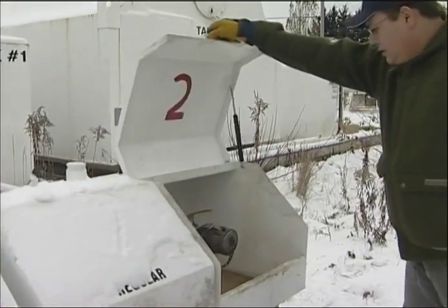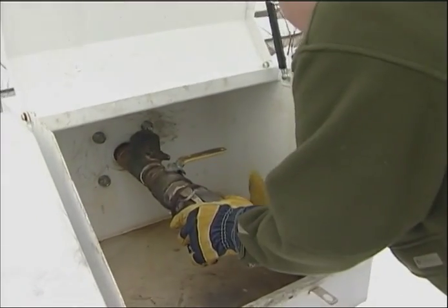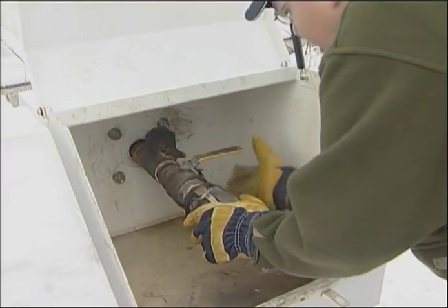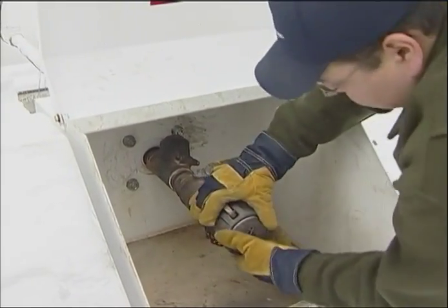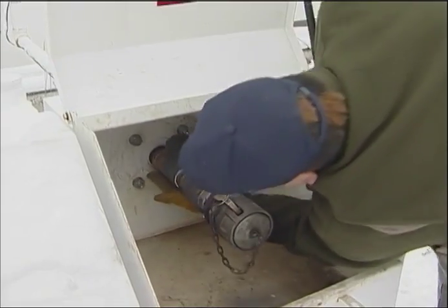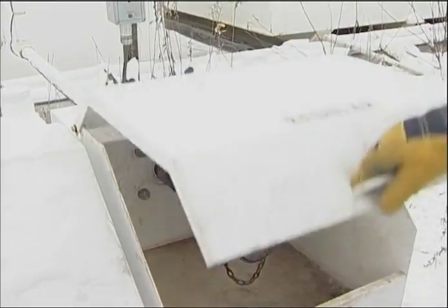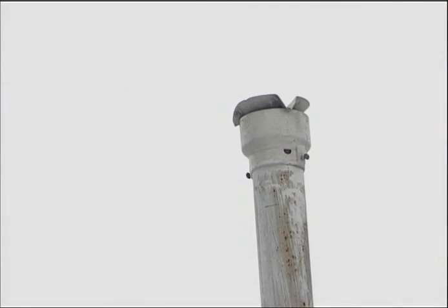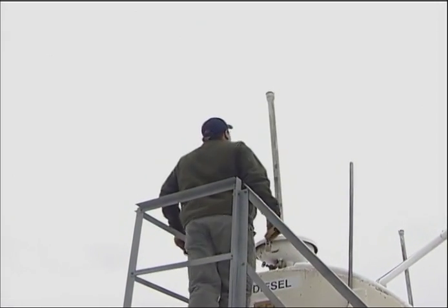Check all fuel shutoff valves to ensure that all valves are in good working order. Check fuel shutoff valves for wear or possible leakage. Check pipe in fuel cabinet to ensure pipe is not leaking, cracked, or worn. Check fuel tank vent pipe to ensure that it is free of obstructions.